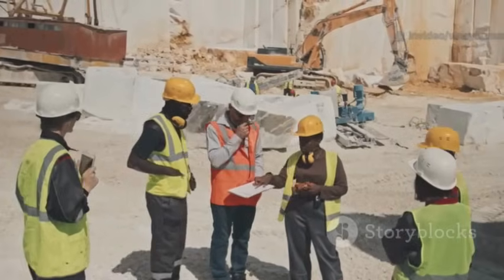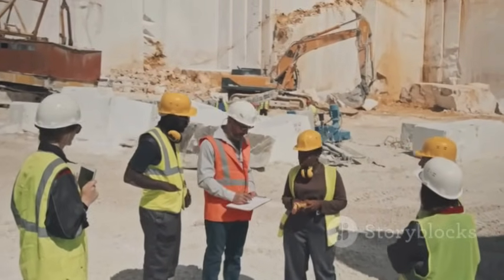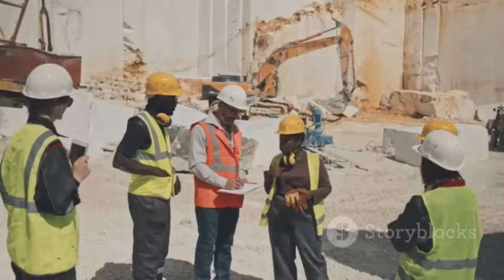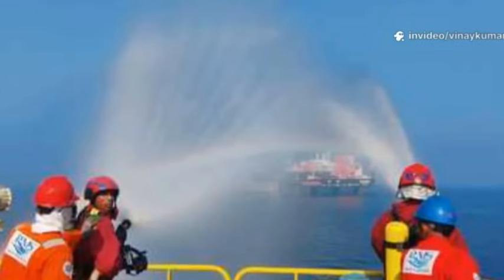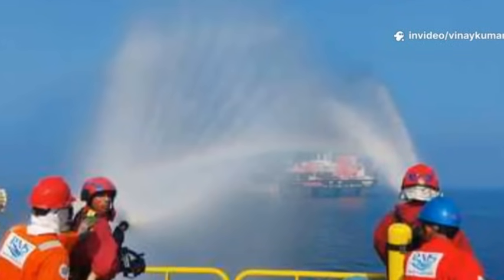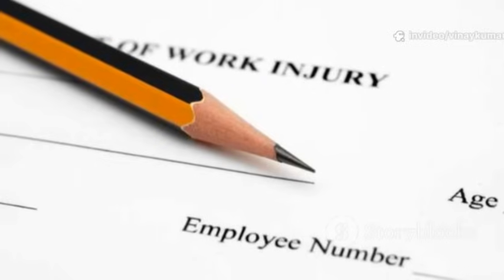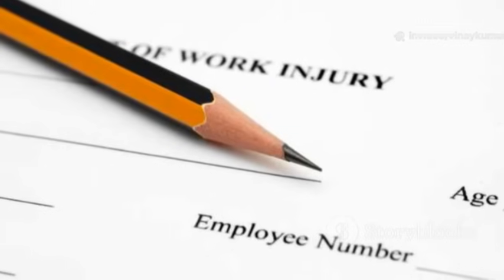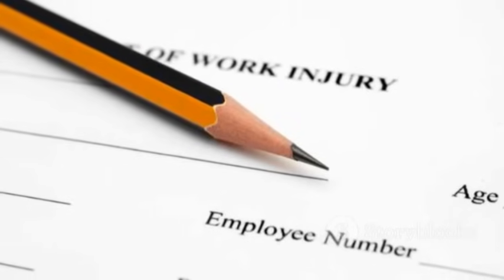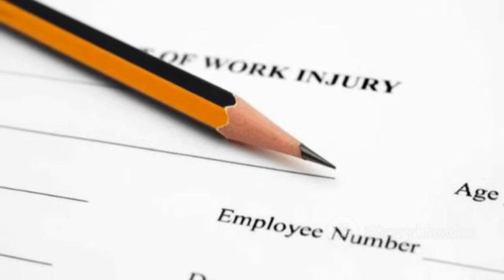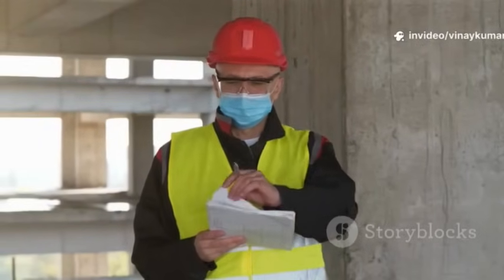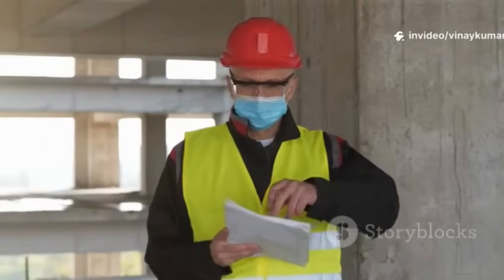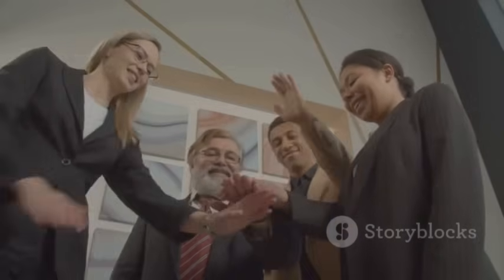Once a contractor is selected, the host employer must inform them of the known potential fire, explosion, or toxic release hazards related to their work. They must explain the applicable provisions of the site's emergency action plan. The host employer is also responsible for maintaining a contract employee injury and illness log related to the contractor's work in process areas. This ensures accountability and tracks the safety performance of contractors while they are on site. It's about making sure everyone is playing by the same safety rules.